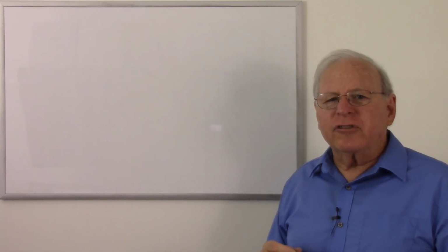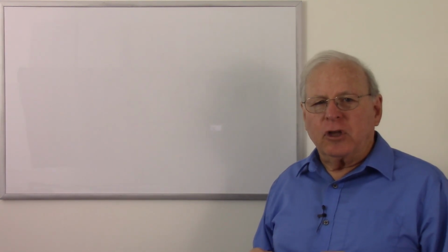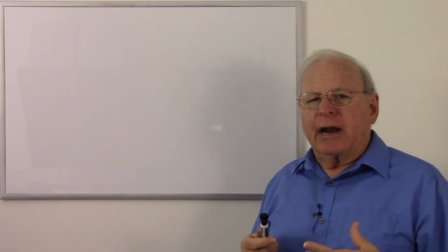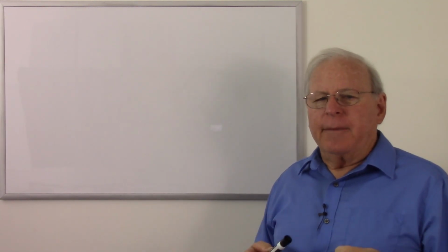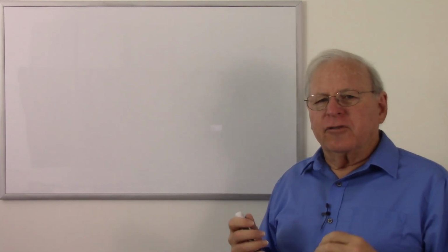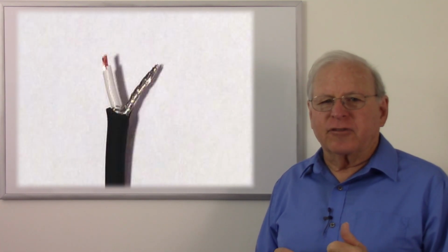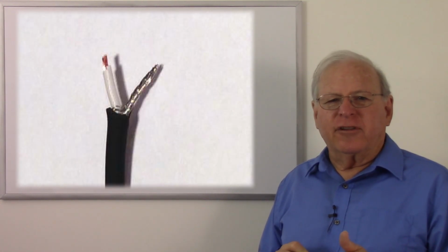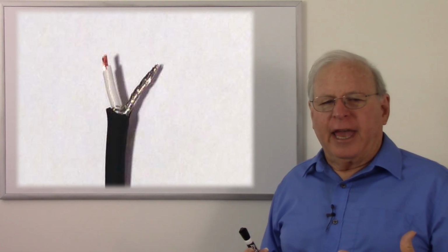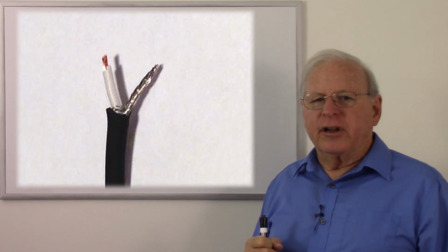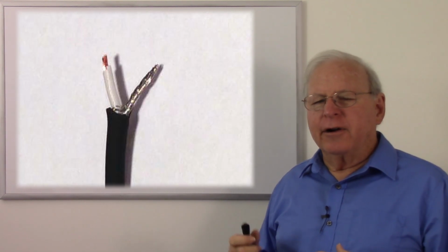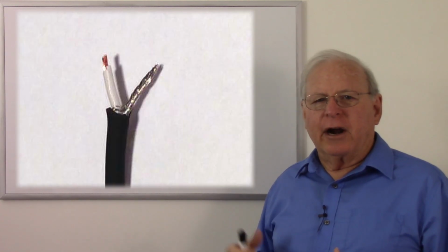So you'll usually see shielded cable used for microphones and tape heads or phono pickups so that we don't pick up any outside noise. And here's a picture of some simple shielded cable. It's not sophisticated like coaxial radio transmission cable where the tolerances are very tight. We just have a shield around a wire. The shield is the ground and the wire carries the signal.